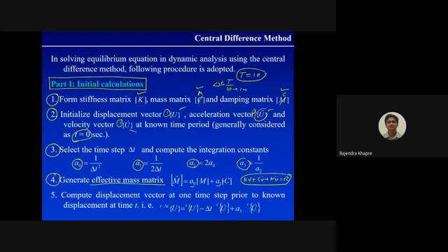Okay, now in this particular step we are starting with t is equal to 0. We have to find out the displacement at t is equal to minus delta t. This is required only once, because it is used in the further calculations. This is the displacement at t is equal to minus delta t, where delta t can be any value which we will be calculating.